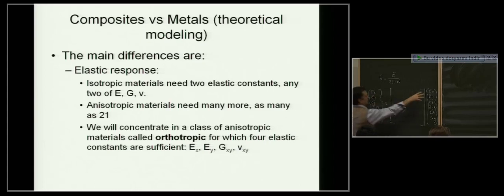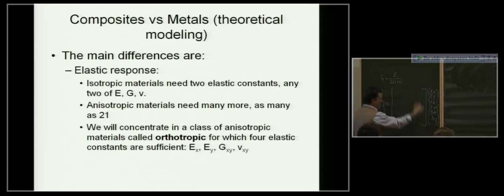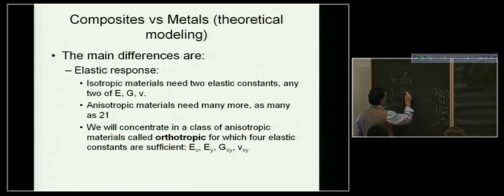So if I'm going to relate those, then I will have a 6 by 6 matrix here. Is there enough room? E13, E14, E15, E16. And it's a symmetric matrix. So if it's a 6 by 6, and you calculate the terms that are the same because of symmetry, then you are left with 21. Conceivably, above the diagonal, including the diagonal and everything else, there are 21 terms that could be independent of each other.